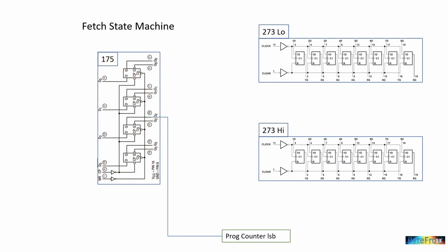We already ran instructions 0, 1, and 2, and are now receiving the PC advanced signal from the last microinstruction of instruction 2. This signal is a value 1 which is sent to D2, the input of a flip-flop labeled 2 in our diagram. As you can see, the current output of flip-flop 2 is a 0, which is sent to act as the least significant bit of a program EEPROM's address input. Hence, right now, the input address to the program EEPROM is 6, as we saw before, and so we're getting the low byte of instruction 3 from the data output of the program EEPROM.